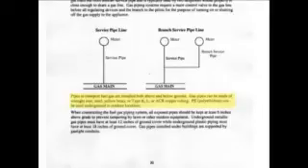Gas pipes can be made of wrought iron, steel, yellow brass, or type K, L, or ACR copper tubing. PE, polyethylene, can be used underground in outdoor locations. It's an important piece to remember for the state exam.